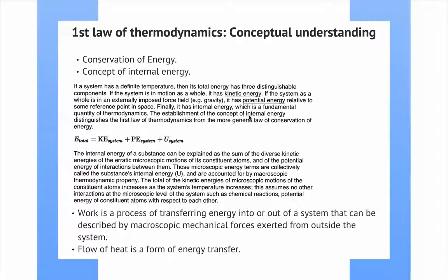So the establishment of the concept of internal energy distinguishes the first law of thermodynamics from the more general law of conservation of energy. So the E total of the system is the kinetic energy of the system plus the potential energy of the system plus the internal energy of the system.